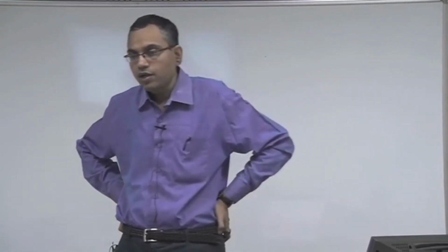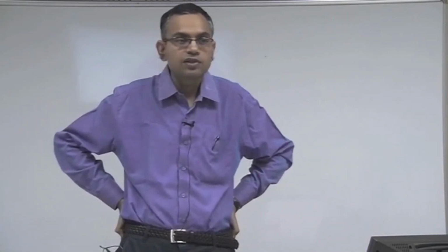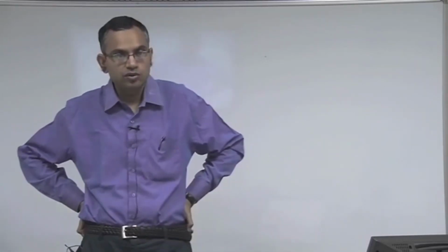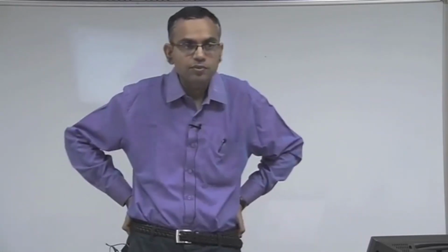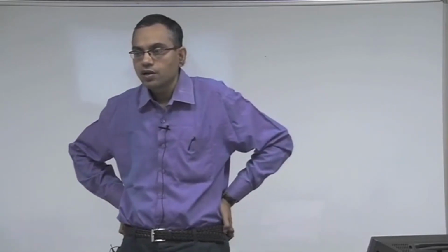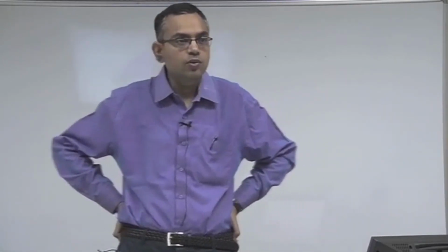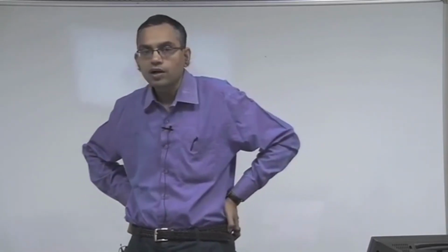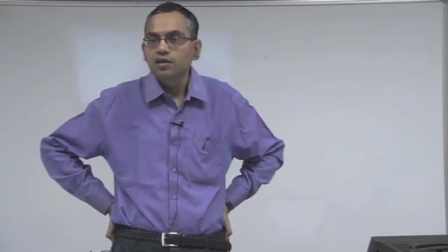Then we started discussing the problem of filling of a nanoscale capillary or a nanopore, which is very important from the nanotechnological point of view, and we revisited the Lucas-Washburn equation with a modification to take into account the nanoscale effects.